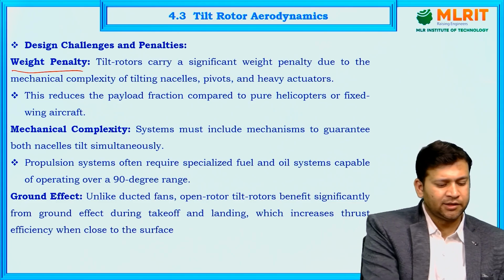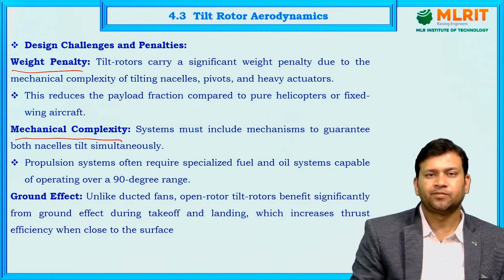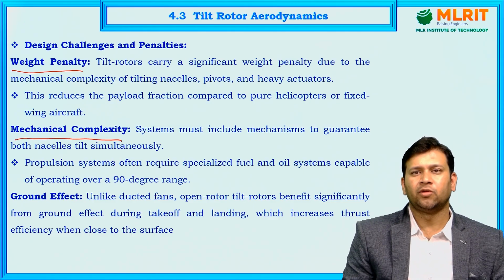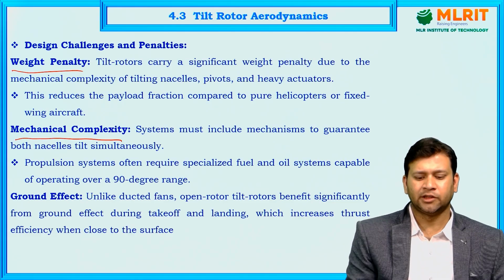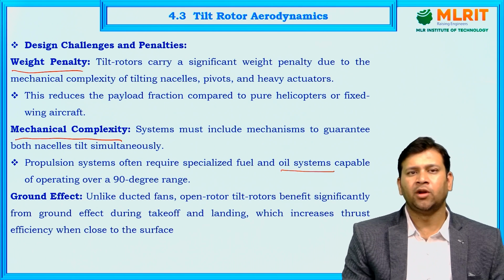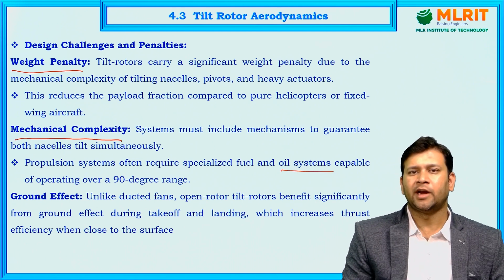The second challenge is mechanical complexity. Systems must include mechanisms to guarantee both nacelles tilt simultaneously. The propulsion system often requires specialized fuel and oil systems which are capable of operating over a 90-degree range.